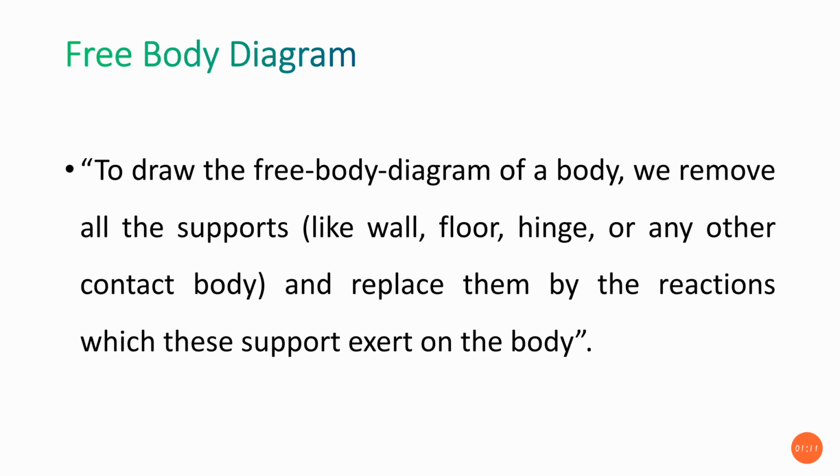For this I would like to define what the free body diagram is. To draw the free body diagram of a body, we remove all supports, such as wall, floor, hinge or any other contact body, and replace them by the reactions which these supports exert on the body.